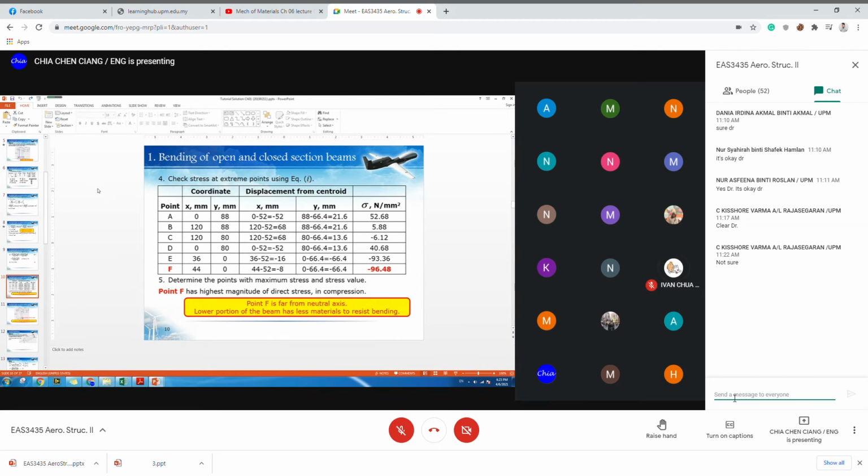Yes, right. So this beam will fail if it is made from a material that can resist a maximum of 80 Newton per mm squared. I didn't mention the positive or negative sign because if that is not mentioned, it means that it is the same in the tensile and compression direction. So I say 80 means that it's plus minus 80 Newton per mm squared.